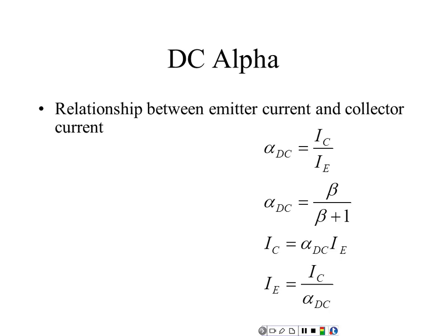So if you're in stereos and stuff like that, you're going to run into both arrangements. Common emitter gives you real good voltage gains, and then common collector gives you real big current gains. Common base we almost never use. I don't even think the book covers common base in here.